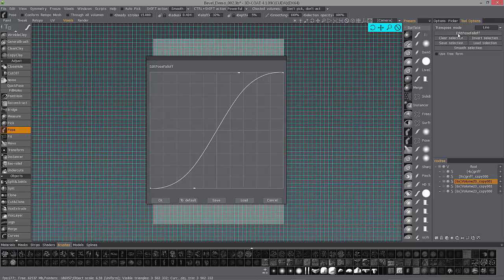And instead of using this trick, you might try and create a different curve shape. And so what you do with 3D Coat, just like you would in Photoshop, you can just click on a point along the spline and it will lay down a control point for you. By default, initially, this is a standard spline curve. The spline will run through the point and there will be a certain measure of curvature, but if you right click once, now you'll notice you have a hard edge. Right click once more over the top of that, and now instead of that spline flowing through the point, it's weighted. It's a B-spline.